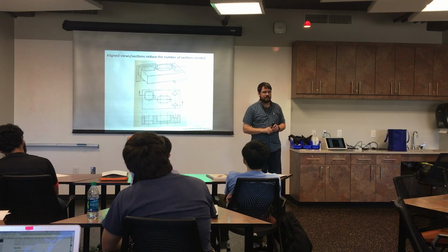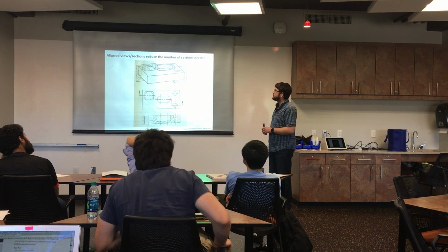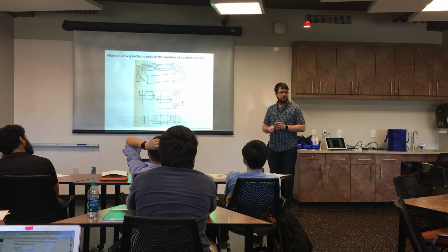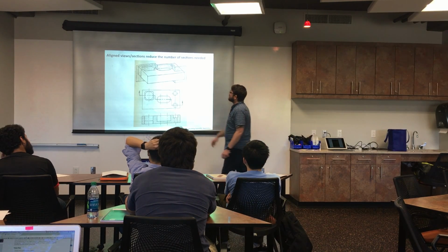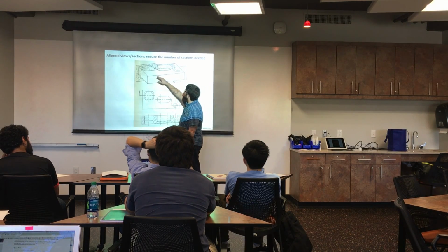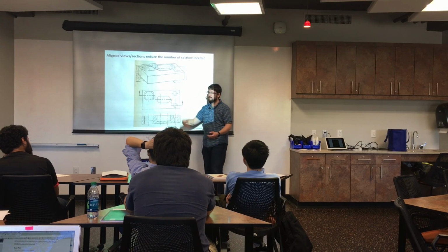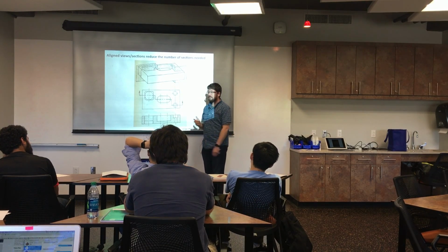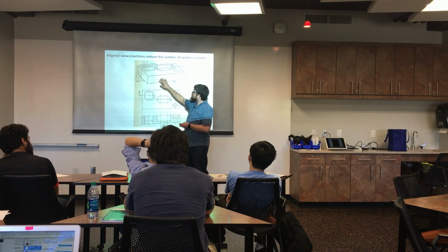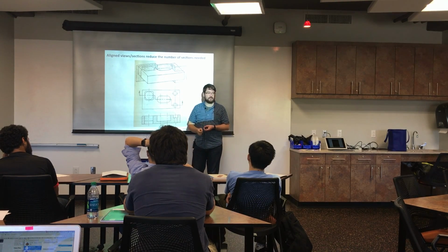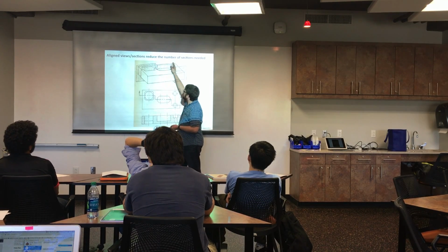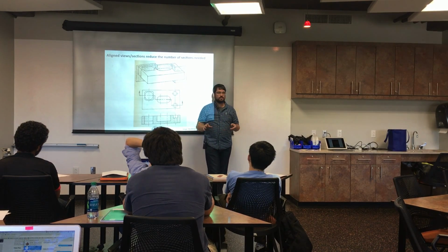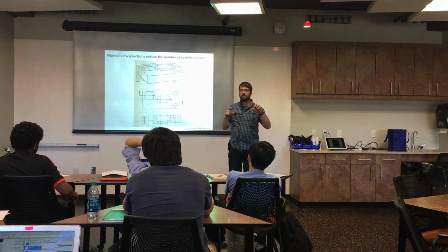We can also do aligned sections, and these can get pretty difficult to visualize until you've looked at the part for a while. In this case, we've got a block that has several pockets in it, so several areas where material has been removed. And the most useful thing to show, if I wanted to show the machinist how deep those pockets need to be, for example, I could take a section through there, and a section through there, and a section through there, and each of those sections would only have one pocket shown on it.